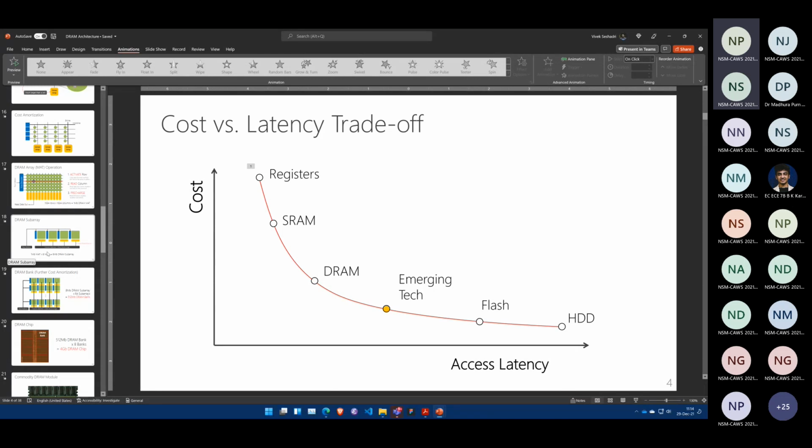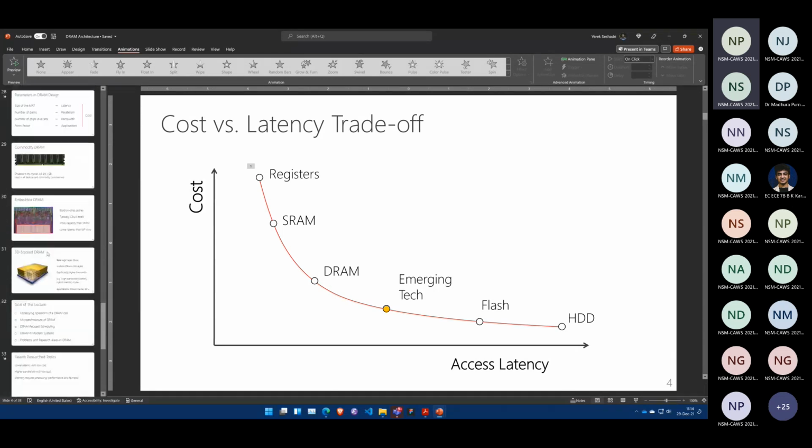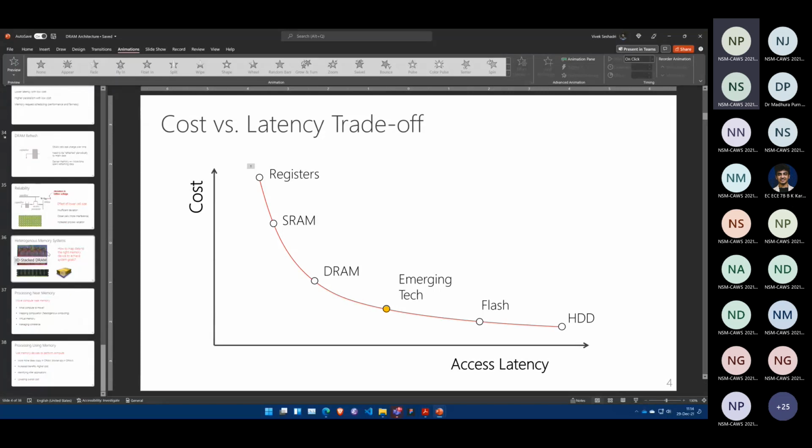What does Intel Optane use? I think it's a resistive memory. So it's a resistor-based memory where each memory element can be in one of two states depending on its resistance. It can either be low resistance or high resistance. If it is low resistance, then it's going to allow more current, and you can detect that. And if it's high resistance, it's going to allow little to no current. And if you can detect that at the other end, you can now store 1 bit of information in that cell, right?